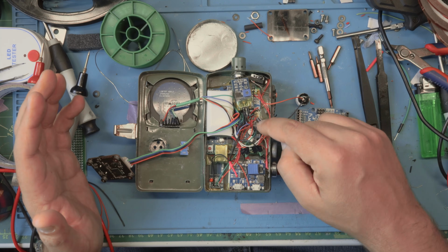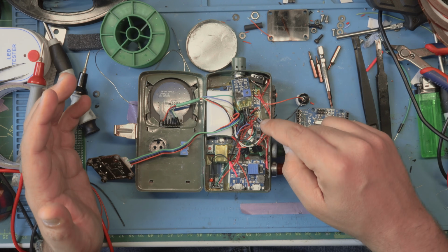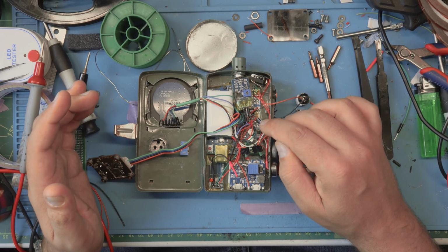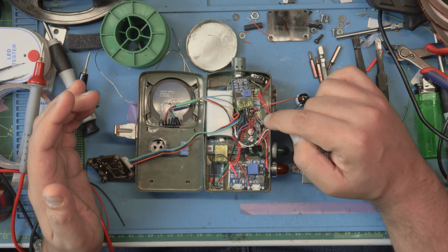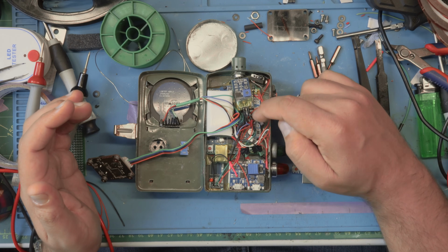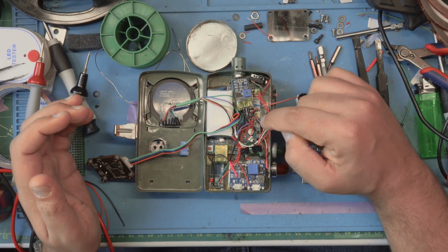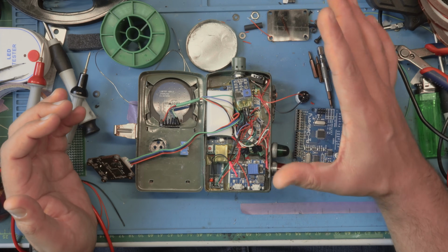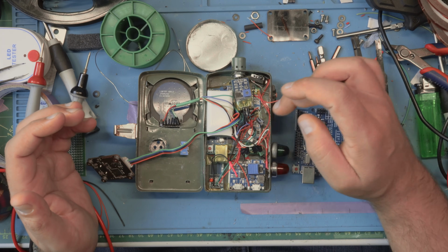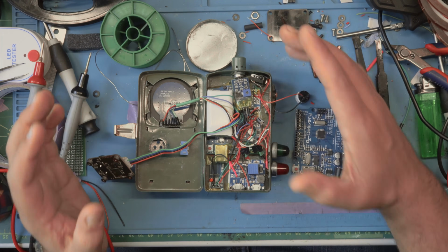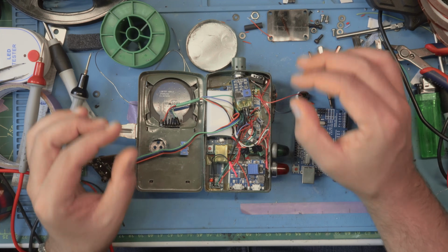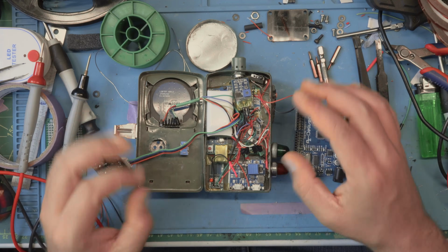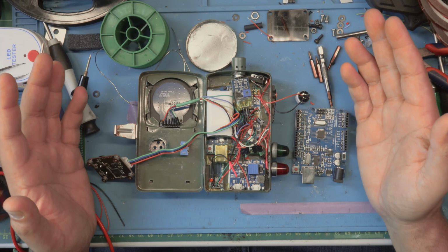It's just a little tiny capacitor right here. It's a 10 microfarad, 50 volt electrolytic capacitor, and you solder the positive pin to the reset pin of your Arduino board and the negative pin to ground. What this does is very simple. It charges the capacitor when I'm turning this thing on, and it delays the boot sequence of the Arduino for a tiny little bit of time, which is just enough to power everything on and then boot the Arduino. And now it finally works.